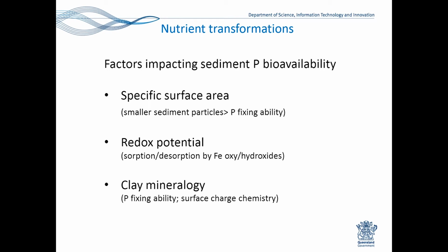And the clay mineralogy is what really drives that process. If we've got clay minerals such as the iron and aluminium oxides or the kaolinite type minerals, the 1:1 type clay minerals, they have what we call surface charge chemistry. They're variable charge. And they behave differently to the clay minerals which we have in our heavy cracking clay soils like our black earths and our vertisols. The clay mineralogy of the soil in the wetland, the clay mineralogy of the source soil of the sediments coming into the system is hugely important when we're trying to understand phosphorus bioavailability.